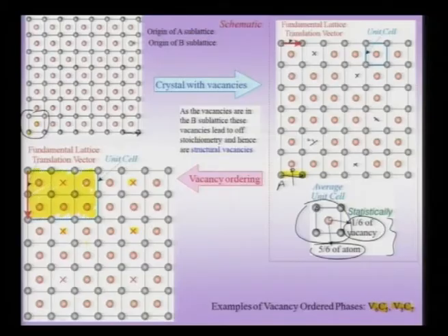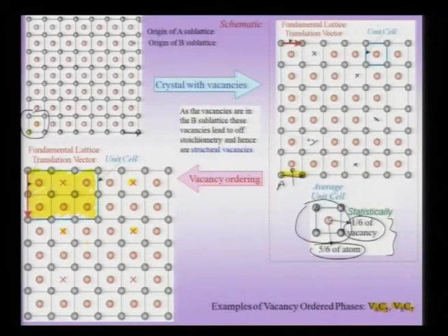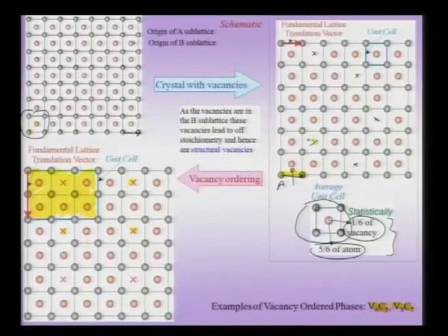In this example we have considered, we should of course note, to emphasize an important point, that the A sublattice could also have vacancies. Some of these vacancies could be thermal vacancies, and some of the others could be structural vacancies which are now localized on the B sublattice, and of course the B sublattice also could have thermal vacancies which would remain, even if we are working at stoichiometric composition. Now the vacancy is in the B sublattice, and if it wants to jump to, for instance, a position in the A sublattice, which would mean that an anti-site defect would be created, the 2 positions for the vacancy are non-equivalent. So that is something which we have to note, and this would cost energy.